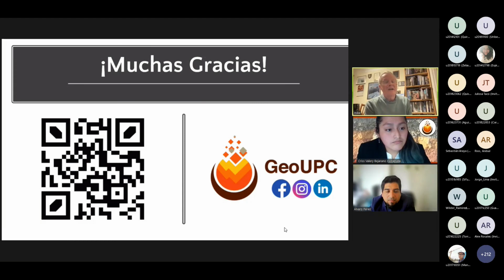Cyclic loading, you need additional parameters. The procedure I have seen most people using now for cyclic loading is they do cyclic simple shear tests, or cyclic direct simple shear tests, and they then calibrate directly to those. In the case of NorSand, we pick up a rotation parameter, and you need to kick that in. You'll find the FLAC implementation of NorSand, I think, has got the principal stress rotation parameter in it.